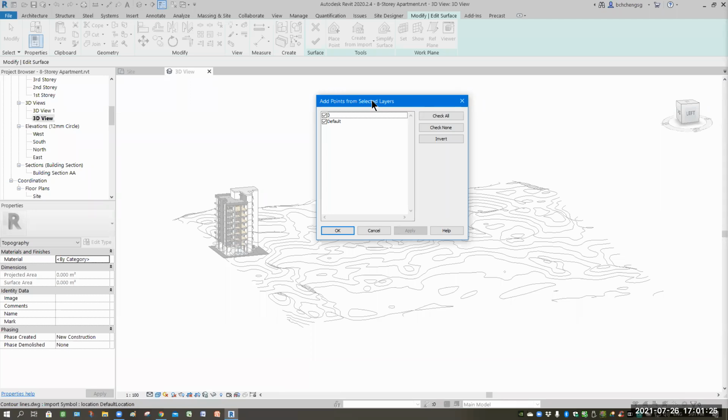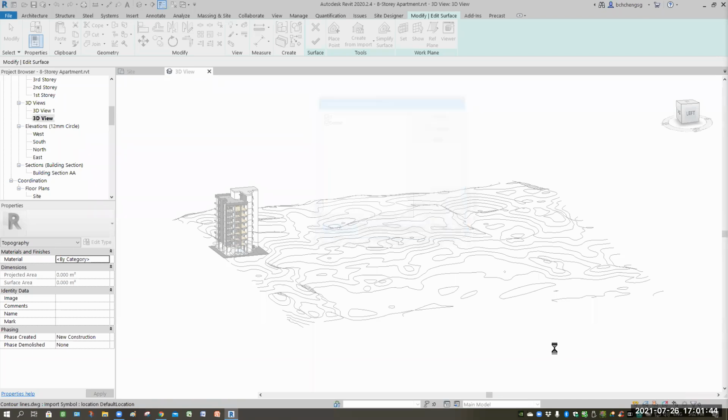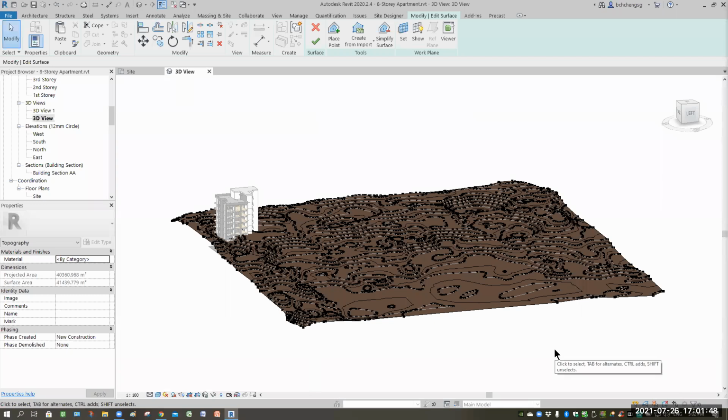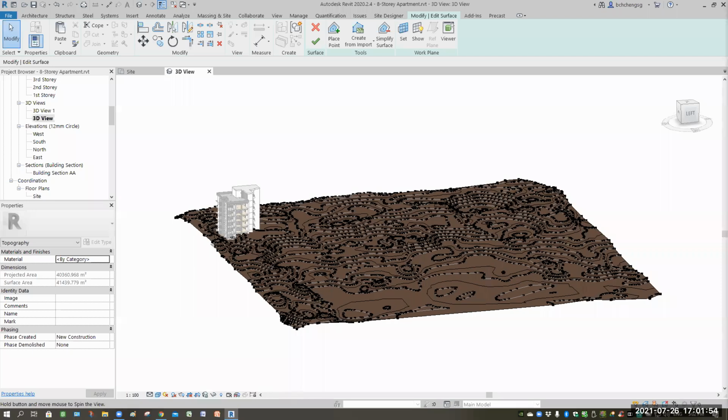So the surveyor needs to plan the layers correctly. Then you only choose the layer of topo information you want to convert. For my case here, I have cleaned up, meaning the unwanted ones I already deleted. So you pick okay. It's converting now. Done already. See? Like that.